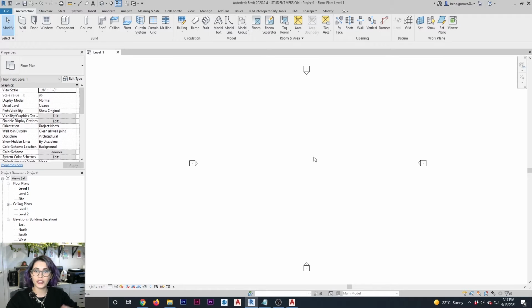In other words, there's usually going to be some reference information that we are going to be using as the base of our proposal. So the idea here is that instead of having to painfully pick up each individual measurement on this existing structure and redraw it in Revit, you can bring an AutoCAD drawing of that proposal and use it as a tracing material.